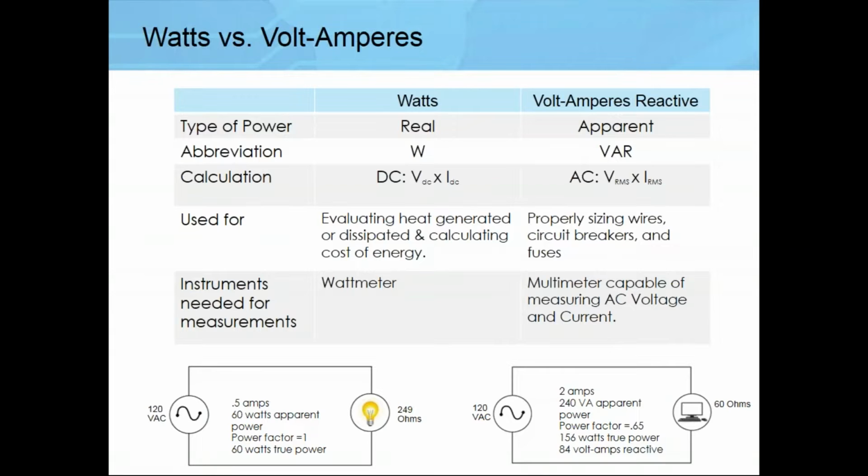If you take a look at an example of a heating element, what does a heating element do? It restricts the flow of the electrons, and in doing so, it heats itself up. So when current flows through this heating element, the electrons energize the heating element, and the heating element is releasing energy. Now, this is a purely resistive load. The majority of the power that you deliver to this heating element is going to be used to heat up the environment, or heat up the stovetop or oven in this case. So this is what we call real energy being used to deliver real power.